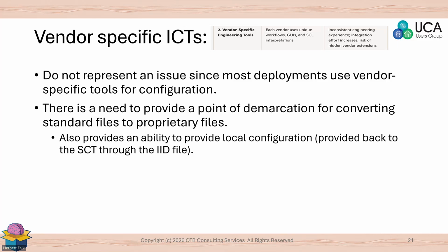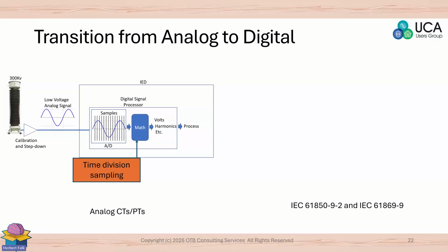Vendor-specific IED configuration tools don't represent an issue because we're all already using vendor-specific tools for configuration. There needs to be a point of demarcation from converting standardized files to proprietary files, and that's the purpose of an ICT. So let's talk about the transition from analog to digital.